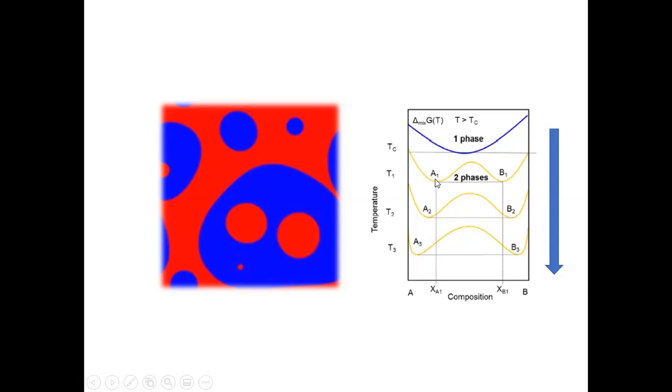The reason is that you have competition between entropy and enthalpy considerations, right? But whenever you have this double local minimum, we know that thermodynamically the system wants to separate into two different phases, favoring different distinct compositions, A1 and A2. Overall, there's still one microstructure, but two distinct compositions. So that's basically the free energy and phenomenologically what happens for the spinodal decomposition.